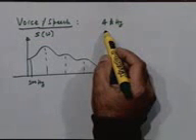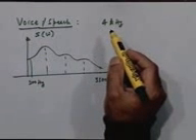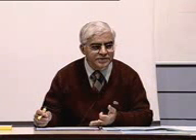In terms of bits per second as a measure of information, it is a really very small amount. It's something like 100 to 200 bits per second, which, as you can see, is very, very small compared to 4 kilohertz, right? This is 4,000 and that is 100 to 200. There are orders of magnitude difference between the information rate that is coming out and the actual rate of variation of the signal itself.